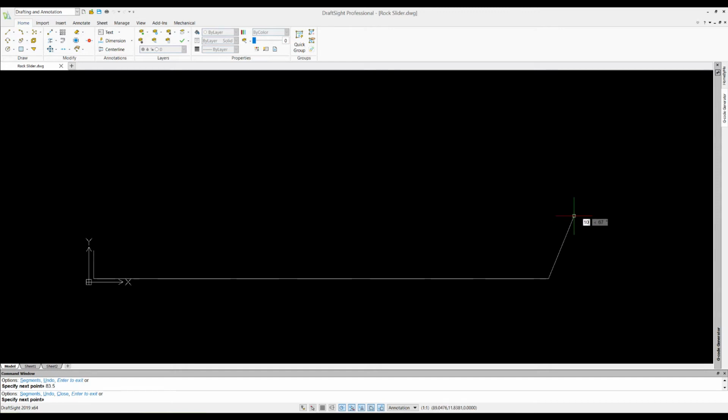Press tab instead, and that's going to go to your angle. So now, straight up and down on this thing is 90. So we want it to be 15 degrees, so 75. So type 75 and enter. And it just drew a 10-inch line, 75 degrees, out in that direction. So just push escape now and get out of that line drawing.